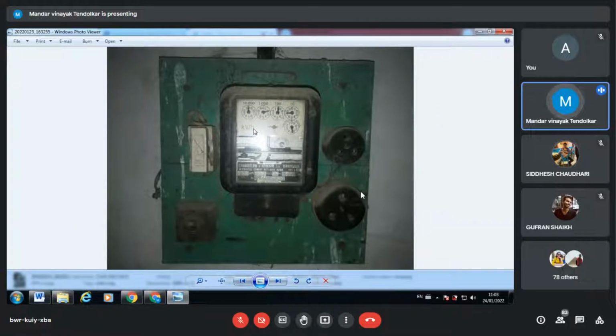So in the actual setup, in the actual scenario, offline mode, I used to put like 3 people for water flow measurement, 3 people for taking the stopwatch reading, 3 people for taking the energy meter reading, and 3 people for having the temperature readings. Inlet temperature anyways is constant, that is a tap water. Only the exit temperature of water, TW2, is to be noted down. This is how we execute the actual experiment.